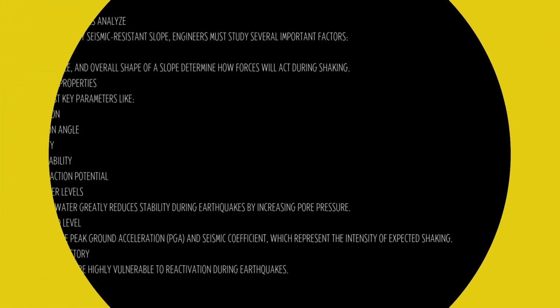Groundwater levels. High groundwater greatly reduces stability during earthquakes by increasing pore pressure. Seismic hazard level. This includes peak ground acceleration, PGA, and seismic coefficient, which represent the intensity of expected shaking. Past landslide history. Old failure zones are highly vulnerable to reactivation during earthquakes.